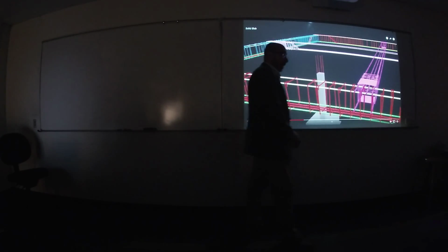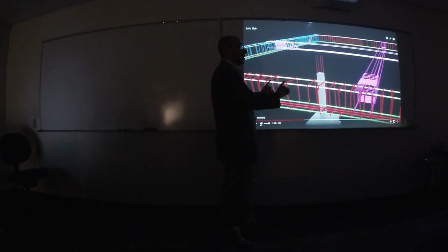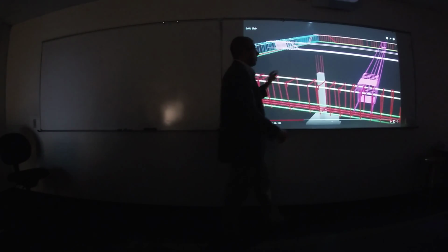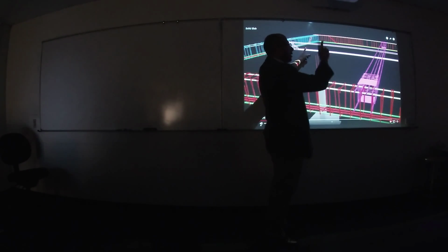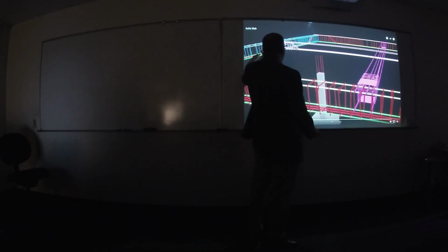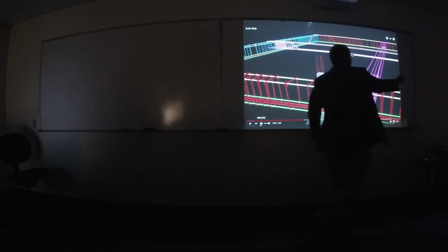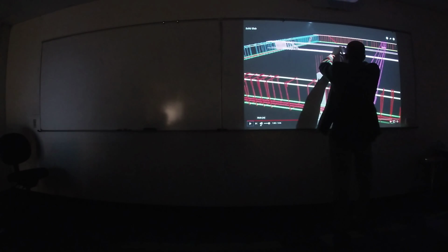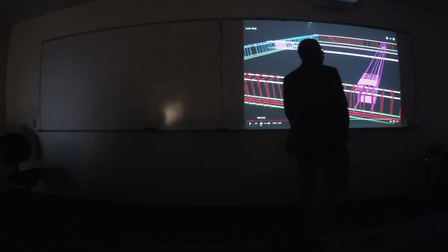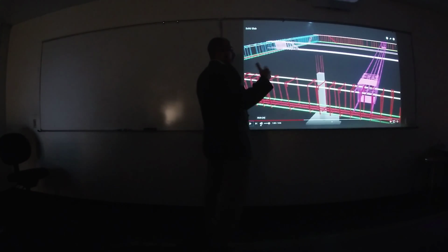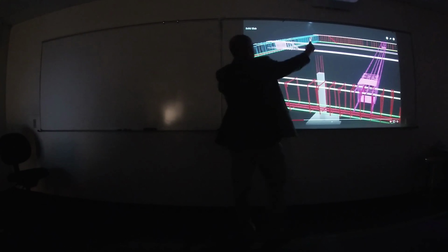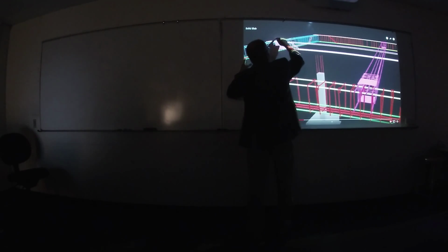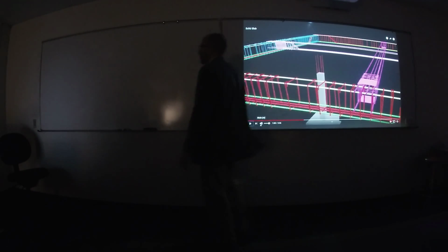Beams and girders. Yeah, these beams are supported directly on your column, but this beam is supported between 2 other beams. So we have a beam here, another beam here, and this longitudinal beam is supported by the 2 beams. If you want to do your structural analysis, this beam will have one concentrated load here coming from the reaction of this beam.